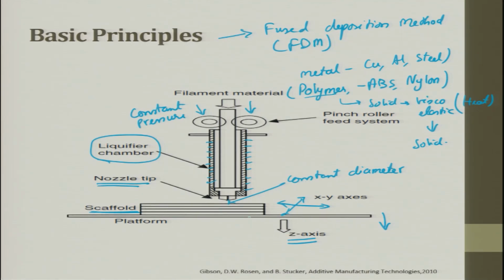Here the constant laying feed rates are dictated by the table movement. So, there has to be a synchronization between the pressure with which it exits out, or the way it exits out, and the speed, in order to get a uniform rod thickness.